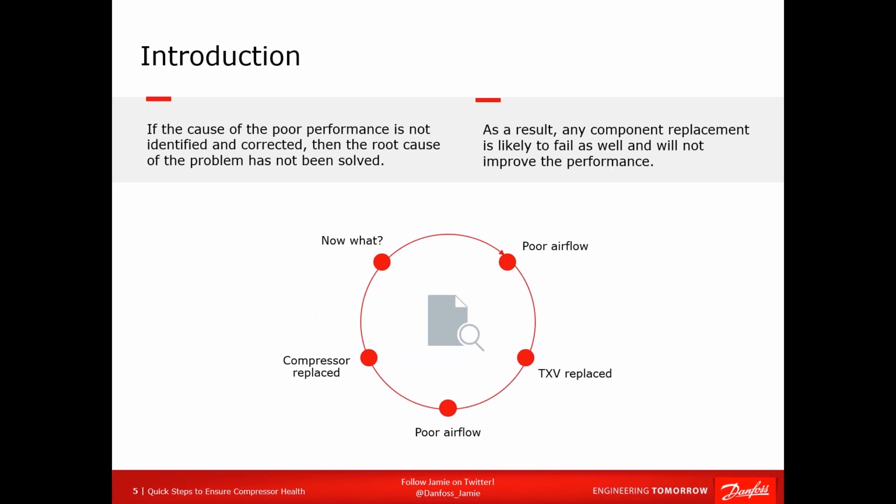So let's say you've got a call and you have a system with poor airflow. Customer's going to complain about it. I got poor airflow. I'm not getting cool in my room. I got high humidity. There's all kinds of issues, the old hot and cold room scenario. So you go there, but he doesn't tell you anything about airflow. He just says it's not cooling correctly. So you put your gauges on the evaporator, you notice that you have low evaporator pressure. What is a good thing to do to increase evaporator pressure? Add refrigerant. So you add some refrigerant, bringing up the pressure. However, you really haven't dealt with airflow.